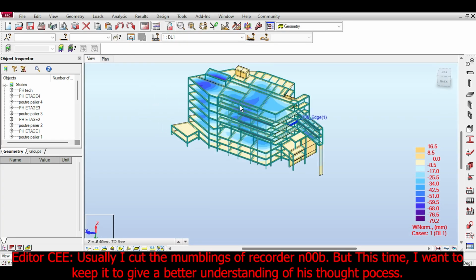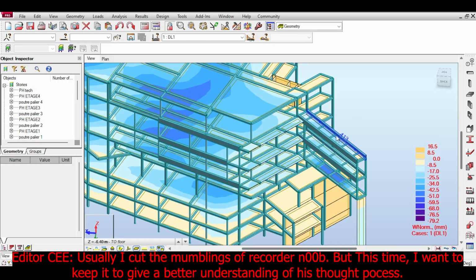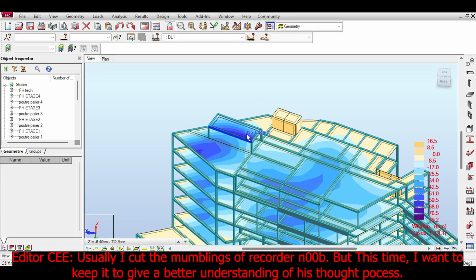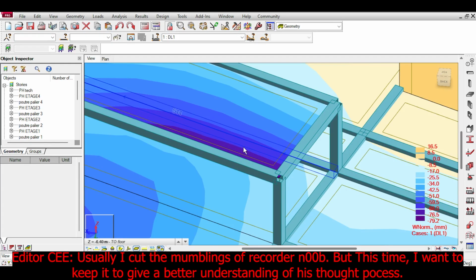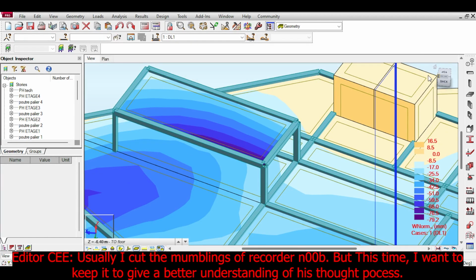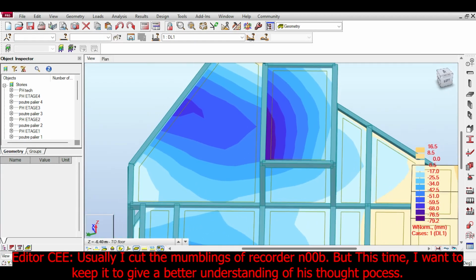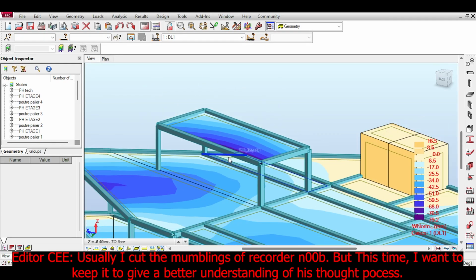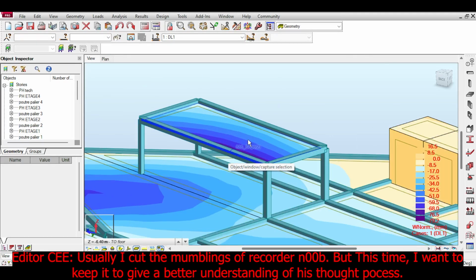Okay, I think it drastically improved. Like there was a big black deflection here, it got better. The only big deflection you have is here. Wait, why do I have a big deflection here? This doesn't make any sense. You have 4 columns, don't you? Oh, that's telltale signs of a slab not being carried. The slab is not being carried, I think. Let me see.